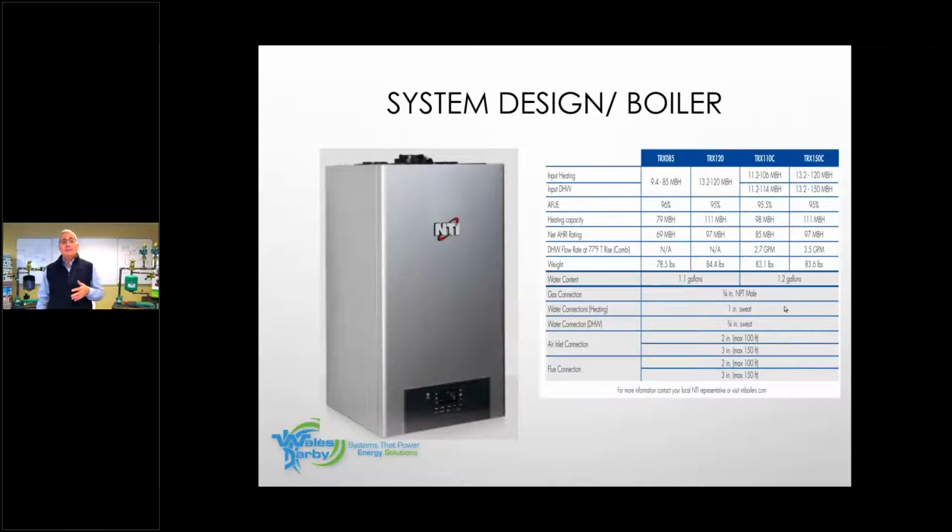And throughout the heating season, the daytime temperature and nighttime temperature is going to constantly change. So if we do a boiler like this, which is going to change its output by the change of weather outside, we can be the most efficient and deliver the most comfort at all times, instead of just making one temperature at all times. So we want to take advantage of that.